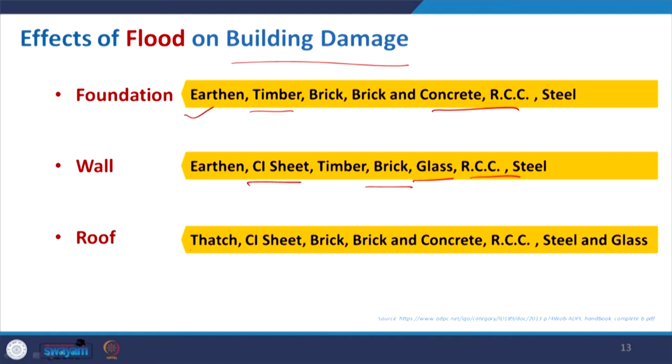So that's true with the roof. If it is a thatched roof and all, with the heavy rain and all, it will not really sustain. Whereas you have a concrete roof, flat roof, that may sustain. And sometimes it is also advisable, whenever your building is to be built in flood prone area, better to go for a flat roof structure, so that at least during that situation people can just accumulate there at the rooftop, and that we have seen in one of the images.